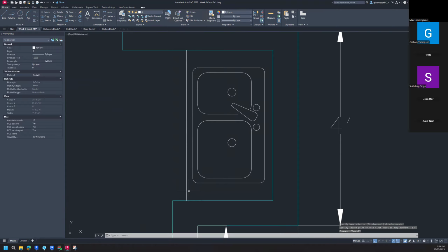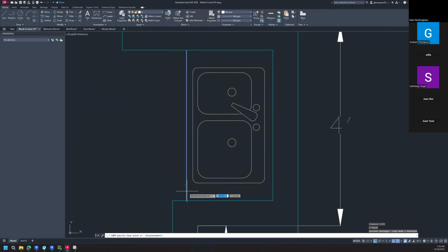And then last but not least, I'll use the same line, copy it from here back to here, and take it and move it a 1/2 inch. Again, I can just go as far as I want or as little as I want, as long as an object snap isn't trying to override where I'm putting that line. All right, so I move it out. I want to move it 0.5 inches.